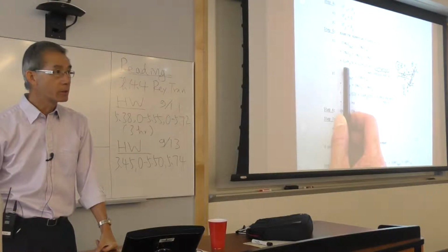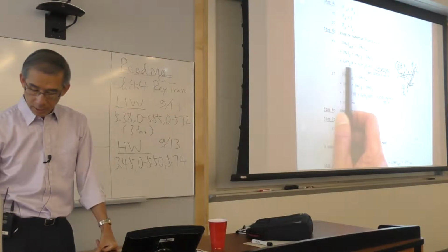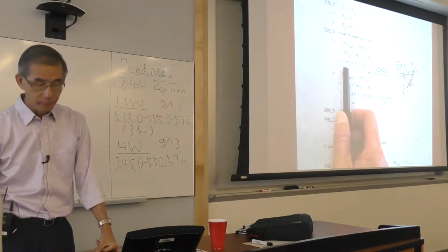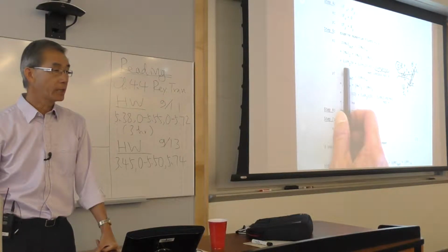What is my m dot in all these 3 terms? Is there a sign with it? No. It's only a scalar. So at 2 it will be rho V, area h2. No sign. Velocity is already chosen to be perpendicular to the area, so I make it very easy for myself.